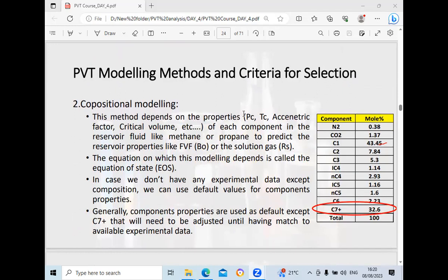So every aspect about the condition of the hydrocarbon has to be defined in terms of the pressure and the temperature, because these parameters will go a long way in defining what that condition would be. If you don't define these parameters, you cannot fully understand how the system will behave. But in a black oil model, we don't need to relate or to understand these parameters that much, because no matter how the pressure and temperature condition will change, these properties within the fluid will not really change that much.